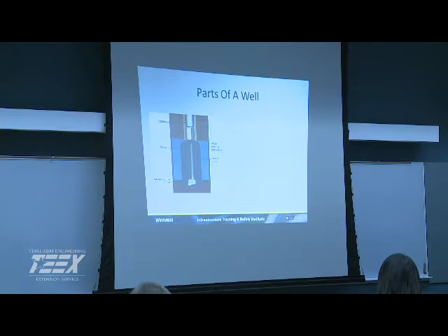Around here, they don't use screens, gravel pipes. We use open borehole. Really? It's a solid rock. Yeah. We pretty much don't have alluvial wells in East Tennessee. Pretty much everything's either coming from caves or fractures.